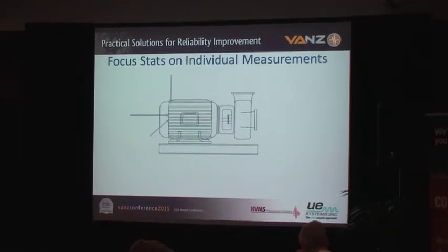The other part of this, though, is making sure that when we take data on machines and do our statistical combinations of things to come up with reasonable thresholds that are representative of true changes in the condition that we're monitoring of these individual machines, we're taking data consistently at consistent operating states for the machine.